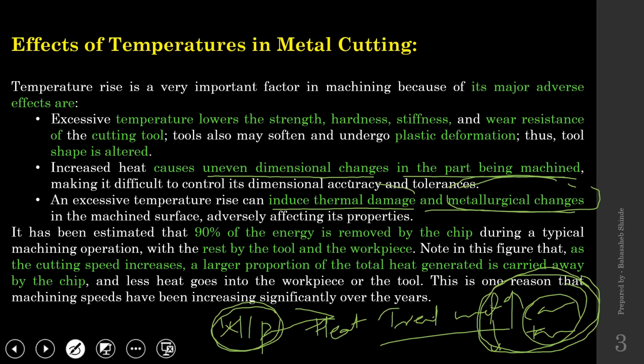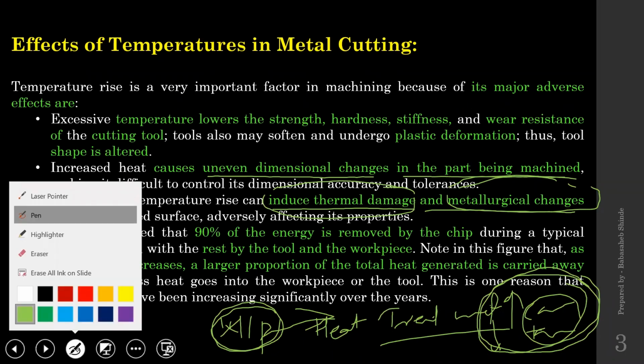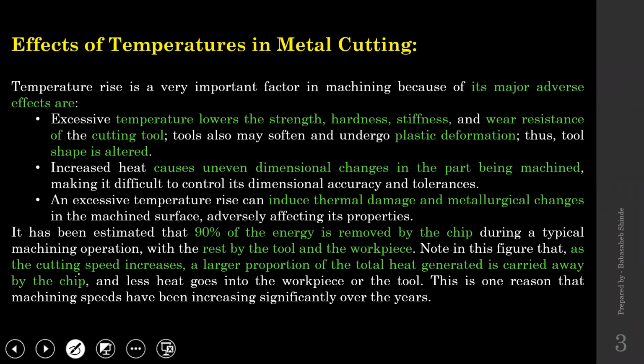Additionally, the thermal damage induced by those heating and cooling cycles is also not desirable, because that thermal damage may be in the form of thermal stresses and cracking of the surfaces, and that is going to reduce the life of the component. Okay, so these are the various effects of the heat generation.